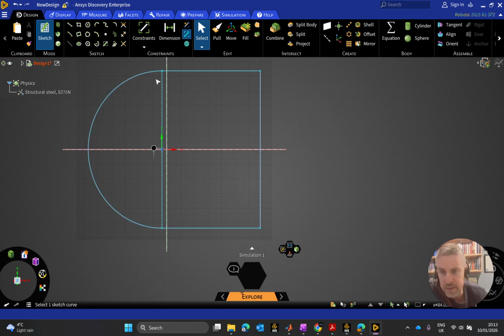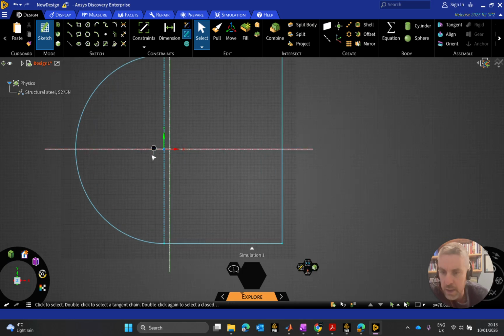So it's space saving. And you can also have circular domains here as well, as opposed to coming out square. But why not use a circular? Well, up here there could still be elements of wake. And if I use a circular, especially on the aft side or downstream of the airfoil, there are areas of interest up here and down here that I might want to maintain. Okay, but up here, potentially not.